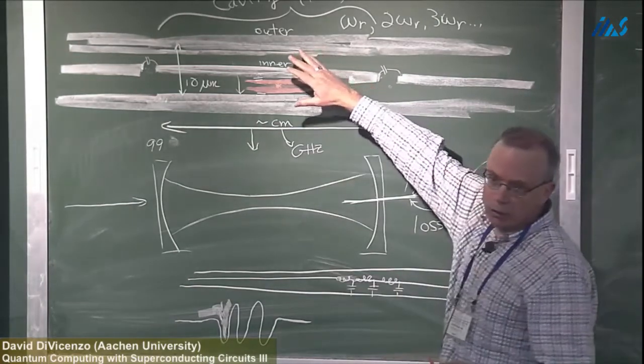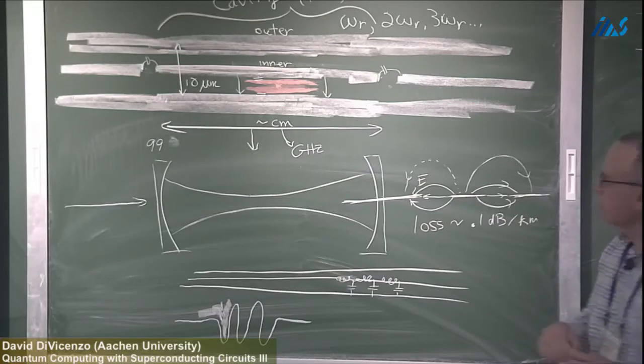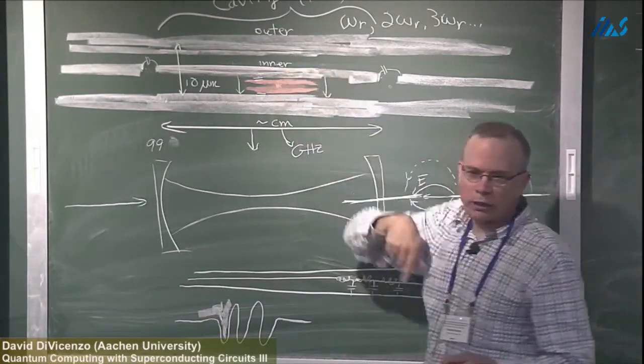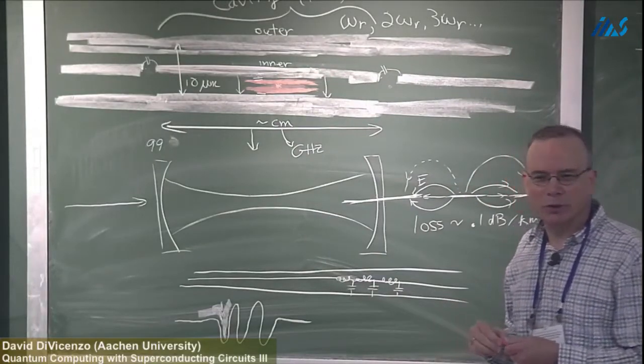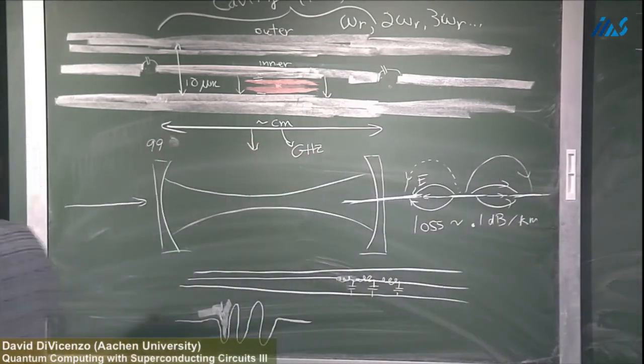Sometimes these are chosen to be different metals, because since this metal doesn't need to have any Josephson junctions, you can use a variety of other superconductors for that. But this, since it ultimately has to connect to a Josephson junction, should somewhere be aluminum, because aluminum is the one and only premier metal for making a Josephson junction. And the reason there's no real need to do it either, if you go into the formal circuit theory that I was discussing, you're allowed to use the usual simplification rules of electric circuits. This is in series with this, is in series with this, but you can commute things in electric circuits. So you could put this capacitor up here, and then there are simple series combination rules. So you really don't need this in the model. And if you put it in, you find that you have a degenerate degree of freedom that you should eliminate anyway.